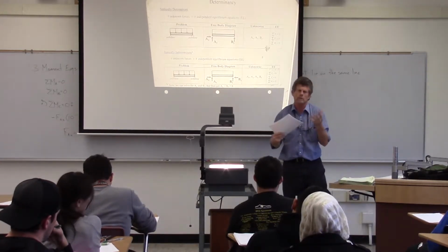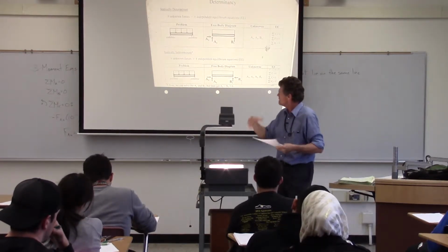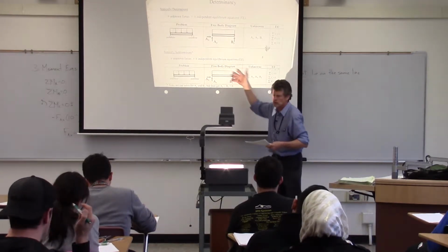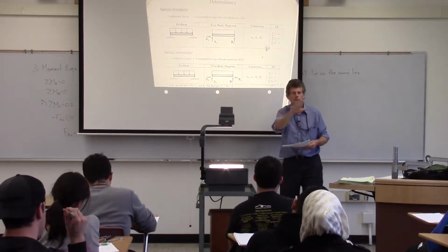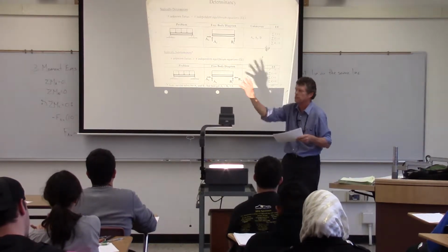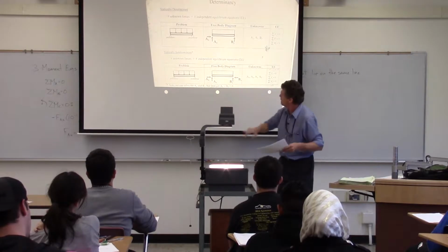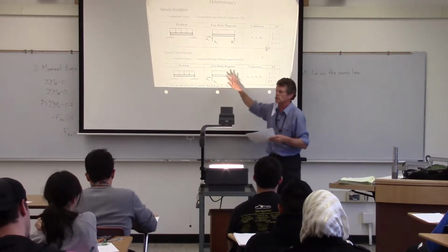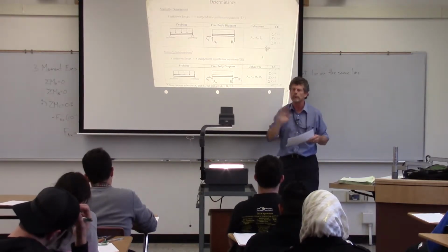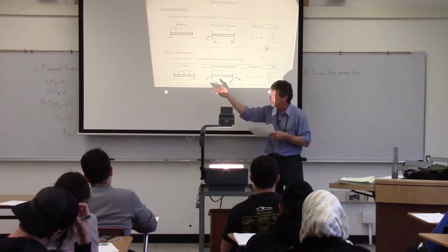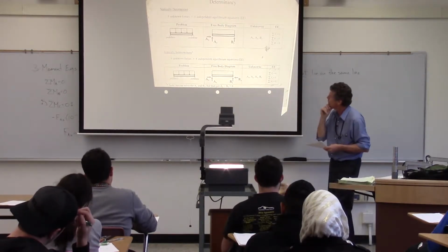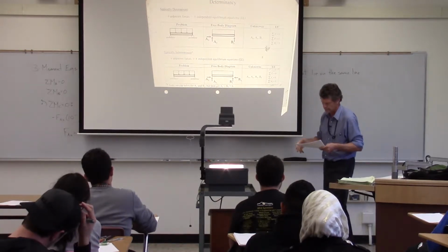So when you see something that says it's statically indeterminate, that doesn't necessarily mean that you're stuck. It just means that you can't solve for everything on that. And what we'll find is when we get into other structures, we're going to be breaking them up and looking at various pieces. What we're going to be able to do is possibly go through situations where there's maybe more unknowns than we expect, but then start looking at other pieces, and then using Newton's third law, saying, okay, well, equal and opposite reaction there, I can go back and start solving for the other unknowns.